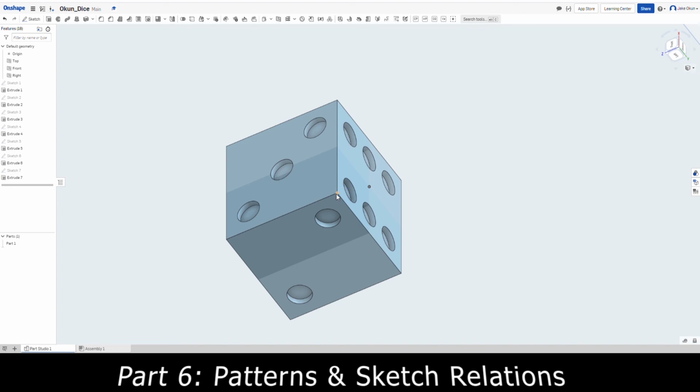Now a fillet is basically whenever you have a curved edge on any object. You can do this regardless if it's a circle, a square, cube, if it's a rectangular prism, if it's a triangle, whatever shape it is, you can create a fillet. It doesn't matter. So now we're going to create fillets. Like I said, fillets are not that difficult to do. So to create fillets, all we're going to do is go up here and you'll see there's a fillet tool. Now don't get confused because there's also a chamfer tool. Chamfer is completely different and that's more of a straighter edge. We want to use fillet, so just select the fillet tool and then you'll notice that this window comes up.